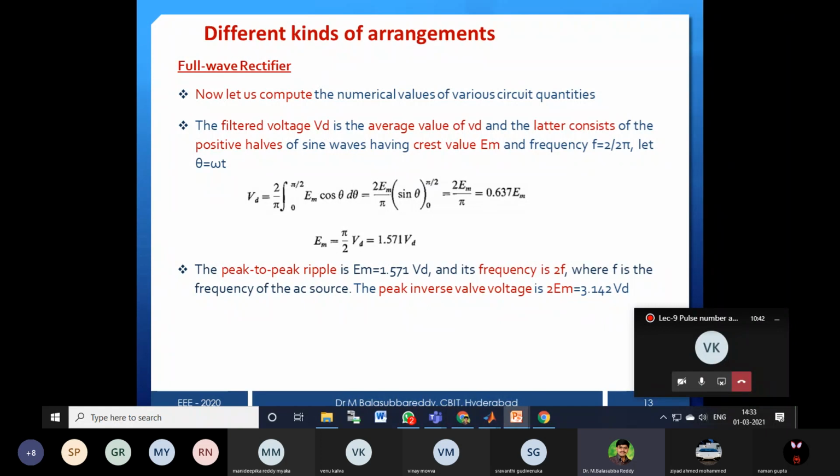When you want to use some application, for the particular load, we need to use valves also. In that case, for midpoint configuration, you will get a higher rating of thyristors that need to be installed. Whereas for the same load, if you connect a bridge type configuration, then the rating of the device is going to be minimized because the peak inverse voltage will be less.